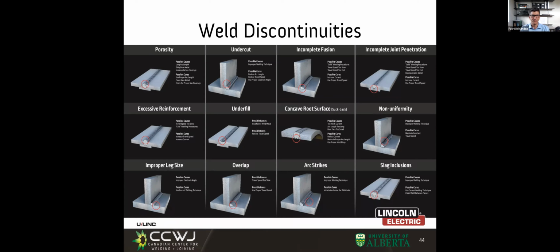I want you to be familiar with what they look like. They talk about causes and they talk about cures. This is not the time to worry about that. I just want to make sure that you would know the difference between underfill and excessive reinforcement, or you would know what porosity is. The other thing is, you see that the title is discontinuities, not defects.